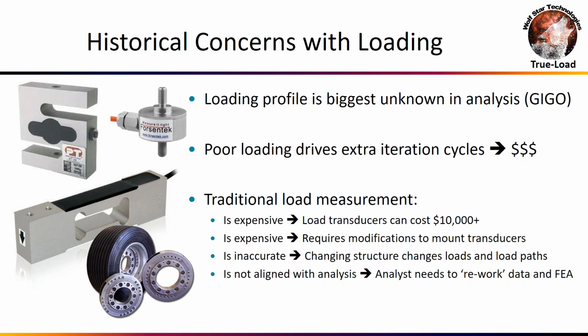But the problem with load transducers is that they can be as inexpensive as a load washer or as expensive as a wheel force transducer at $250,000. And when you bring a load transducer into your system, you're changing your system. You either have to cut out your structure and insert the transducer, or you add a wheel force transducer that adds mass. So you're changing the mass, the stiffness, and the load passing through your structure. You're measuring something, and it may or may not be the actual loads.